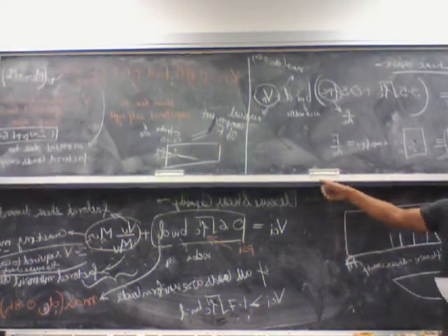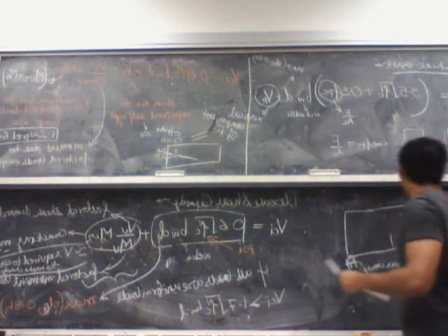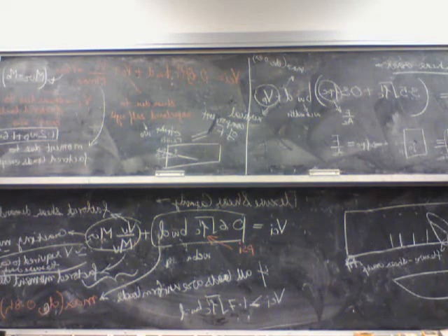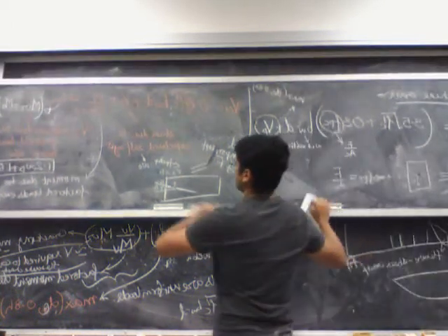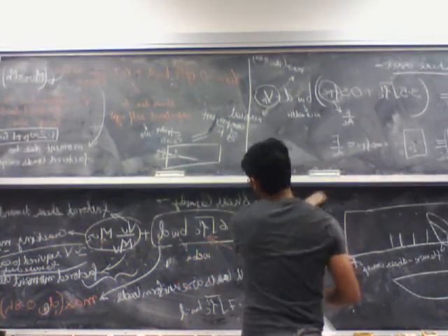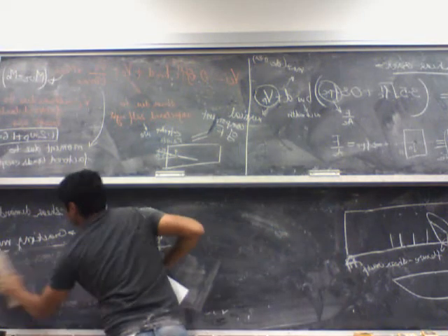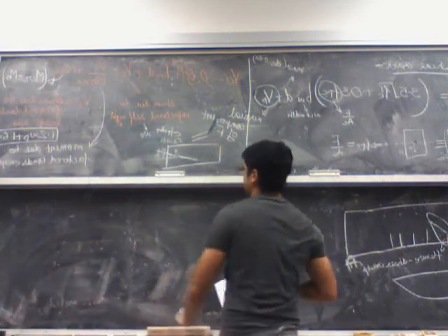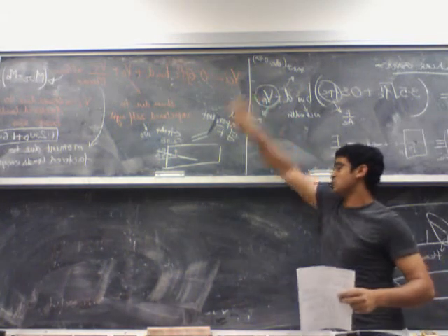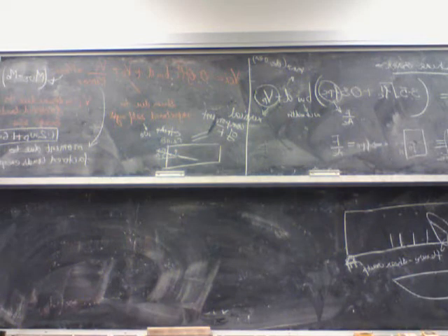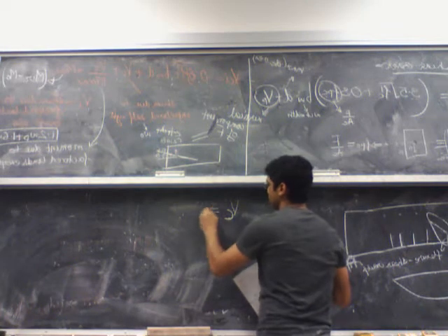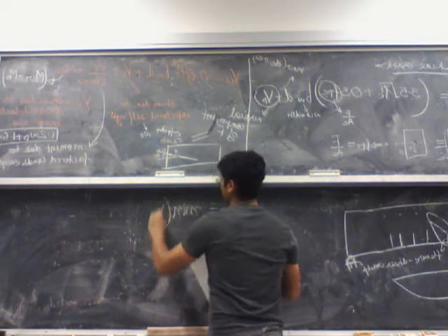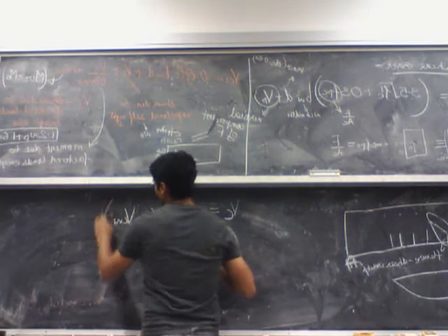So now either this or this gives me the flexure shear capacity. This equation gives me the web shear capacity. So these two formulas, VCI, based on either this one or this one, and VCW, are only accounting for each type of shear failure. Now what we need to do is find out the actual VC, which is the shear capacity of the concrete itself. It is given as the minimum of VCI and VCW.